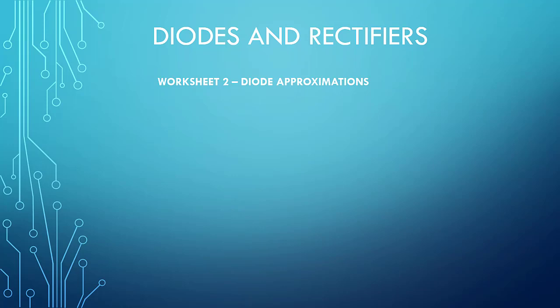But in the real world, we know that when the diode is a go, we do drop some voltage. It has some resistance, some voltage that it's taking. So we see that our diodes in our circuits become 0.3 for germanium diodes, or 0.7 for silicon diodes.